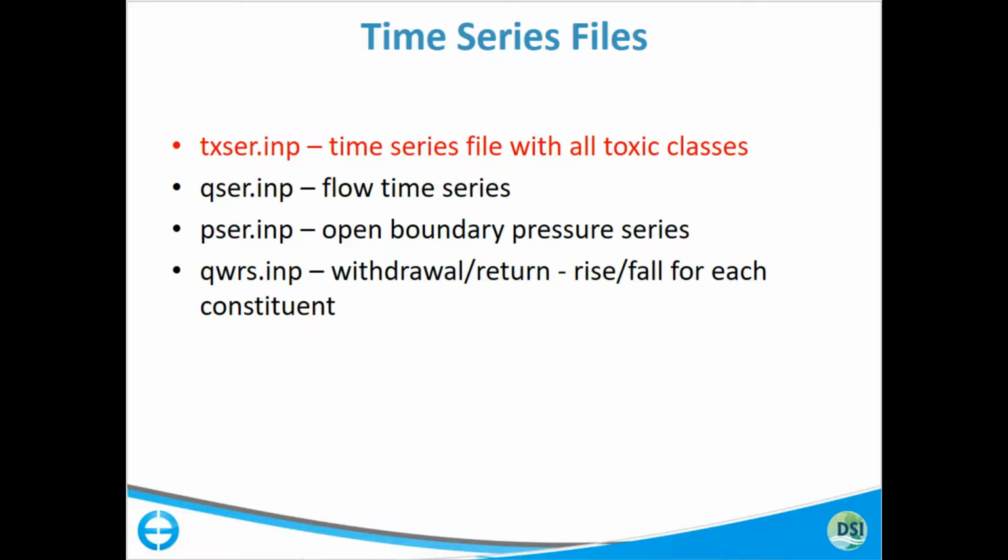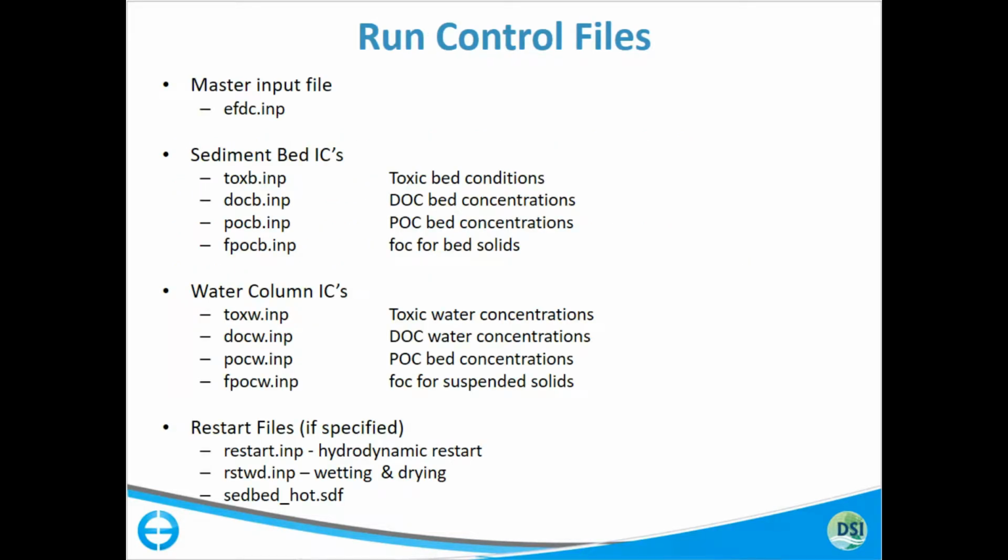Editing any of your initial condition files directly, not a problem. You can do that all day long, but you've got to remember, you've got to reload EE. EE doesn't know if you've got the model loaded and then you manually edit it outside. EE doesn't know that you've made these edits. And if you go and say, okay, well, save, it's going to overwrite what you did manually. So just remember, if you're doing things manually with editors or some kind of processor program or something that you're doing external to EE, make sure you load the model before you do it. Try to run the model so EE can incorporate that information.